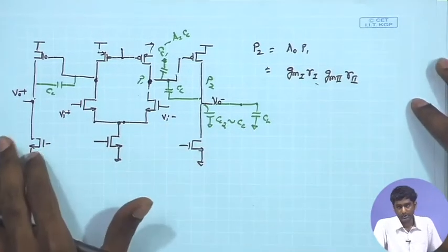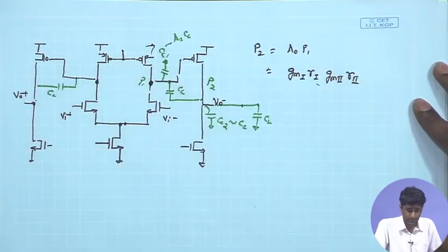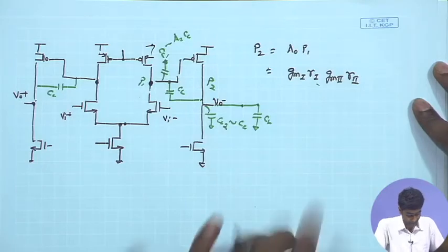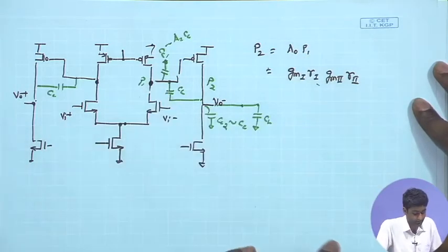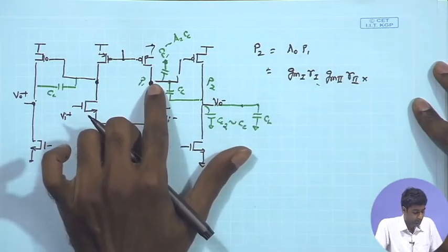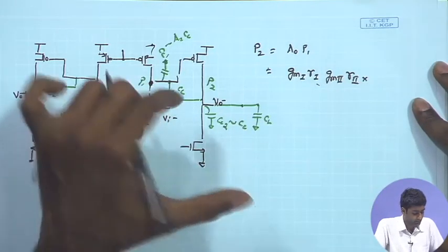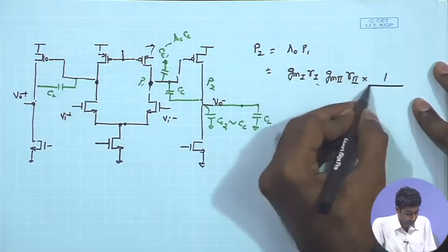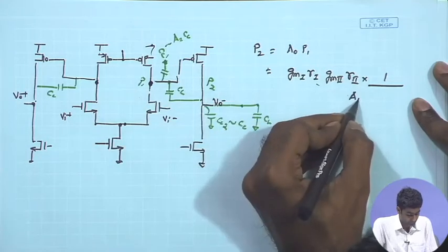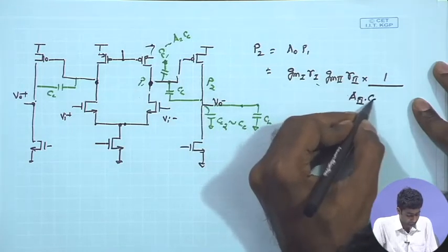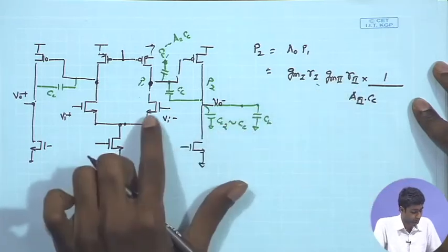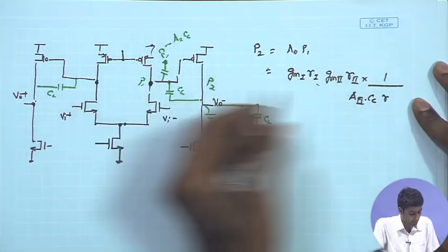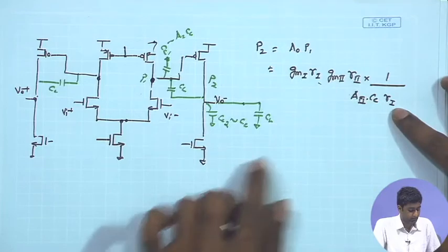I remember, while calculating the low frequency gain, we do not consider the other parasitic components, parasitic capacitances and their frequency effects. And then we also need to find out the P1. So, for the P1, we know that the overall capacitance at this node has been modified as A2 times Cc, which is basically nothing else but GM2 times R2, and then you have the overall small signal resistance still given by the R1.